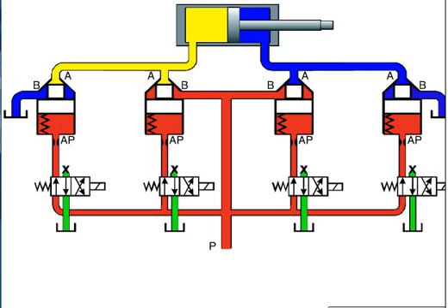For example, the flow out of the rod end of a cylinder is less than from the cap end due to the volume of the rod in the rod end. A conventional valve would have to be sized for the larger flow from the cap end, while the individual cartridges allow you to use smaller sizes for smaller flows. The result is more compact, economical valving.